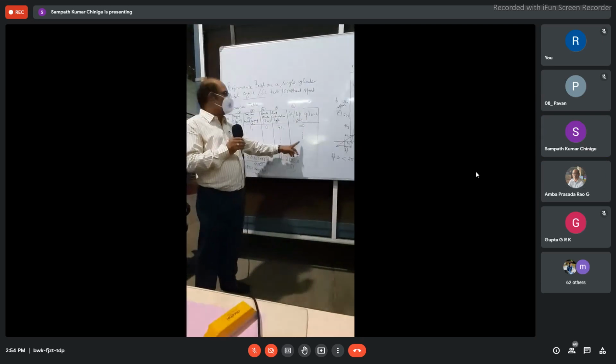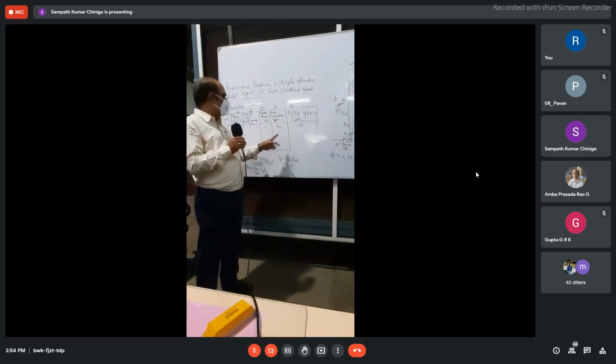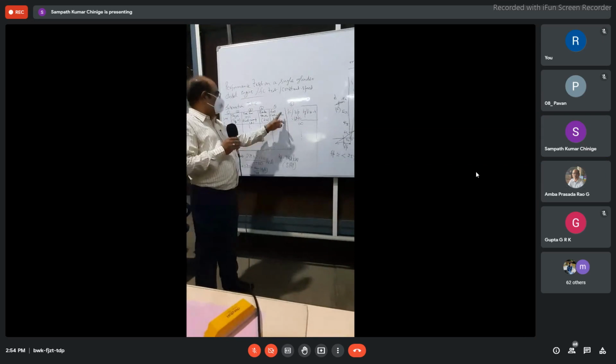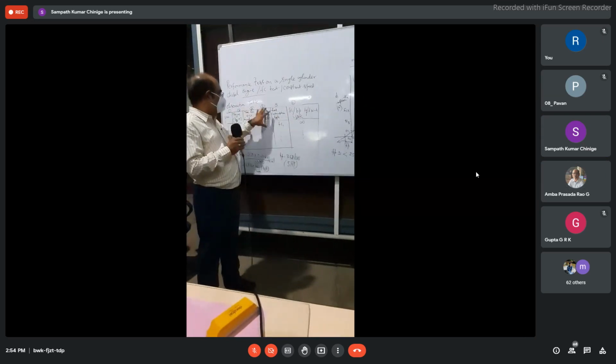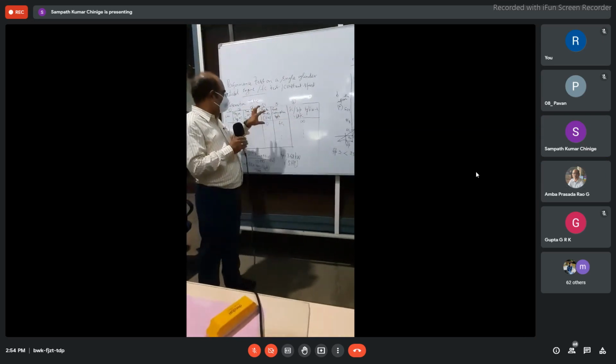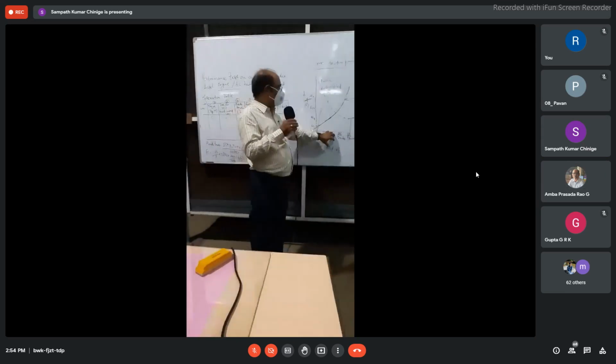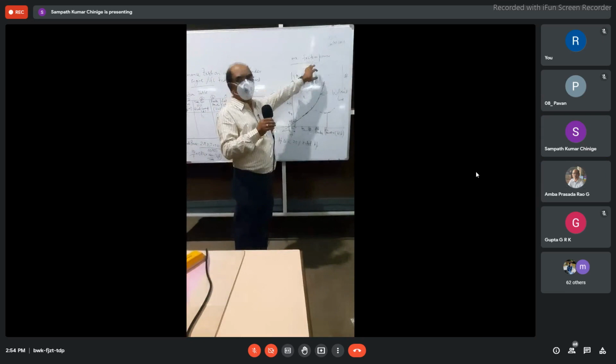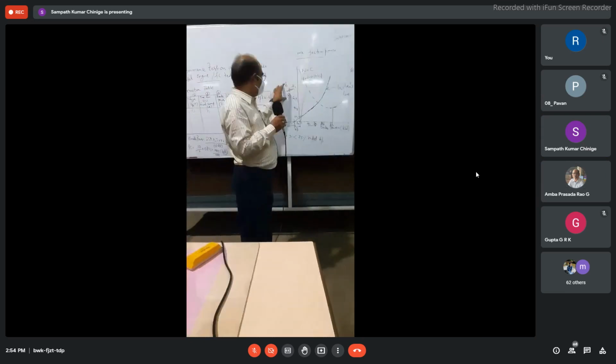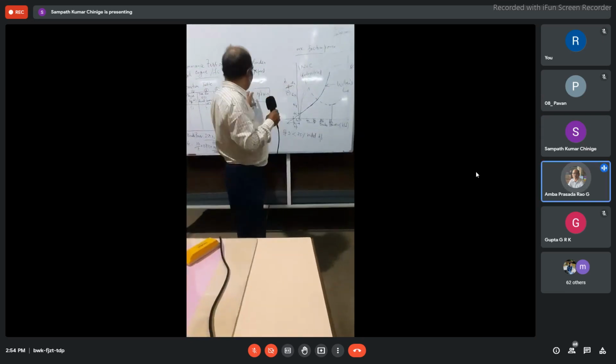So now, what is the fuel consumption for every torque meter reading? You have to forget about the torque meter reading now. You have to concentrate on brake power and fuel consumption. Let us come over here and draw the curve to get the approximate value of friction power.